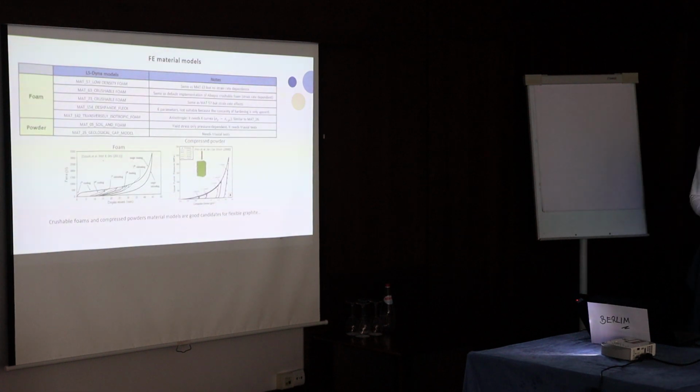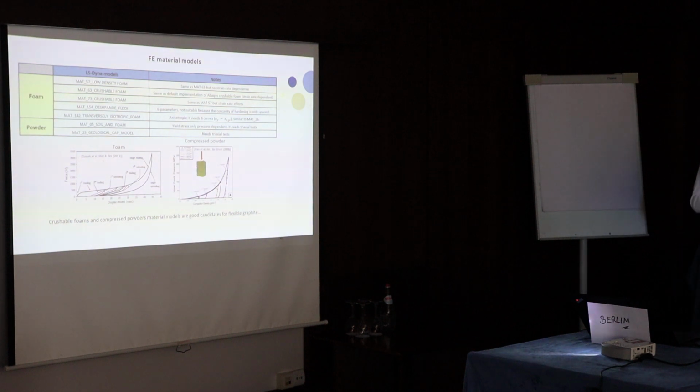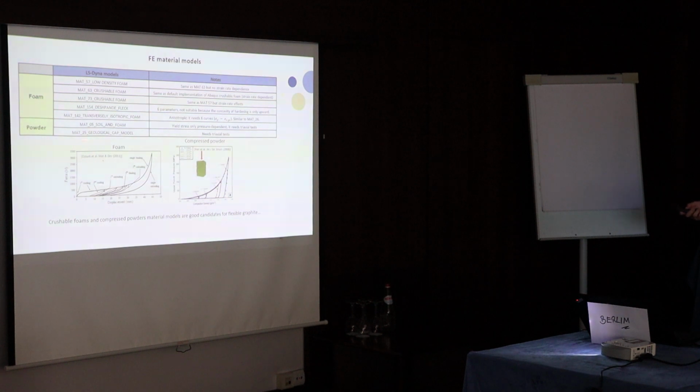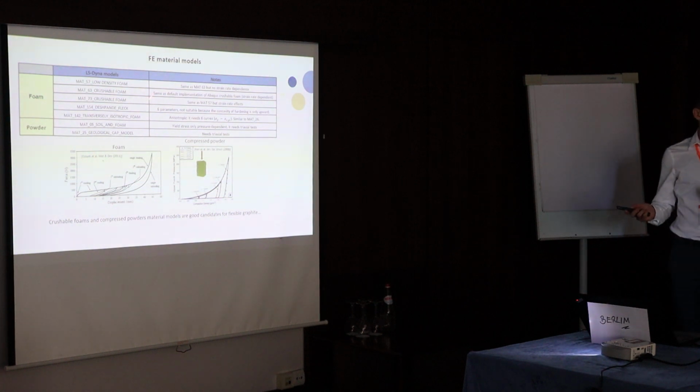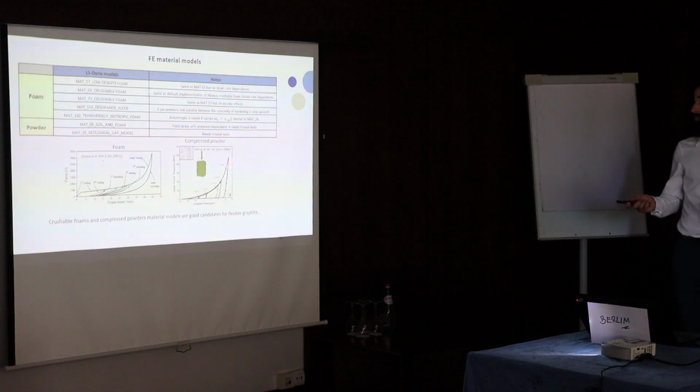So, based on these observations, we did a little bit of a review of what are the material models that can kind of reproduce the same behavior and are available in commercial finite element software. In this case, the software we used is LS-DYNA. And we found that this material is kind of similar to some kinds of foams, crushable foams, and compressed powders.